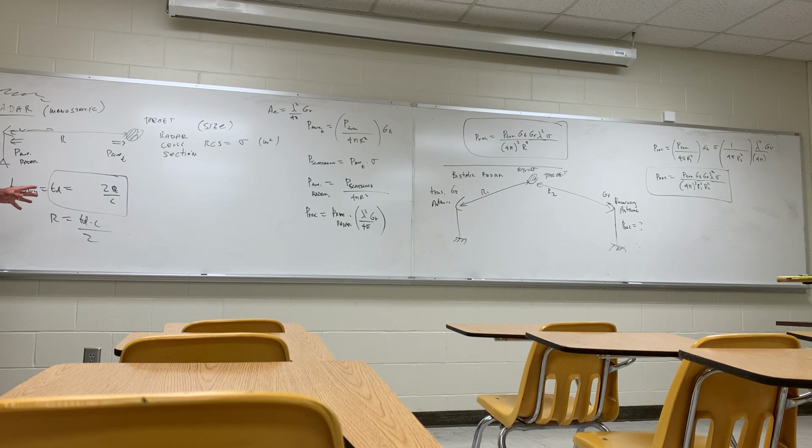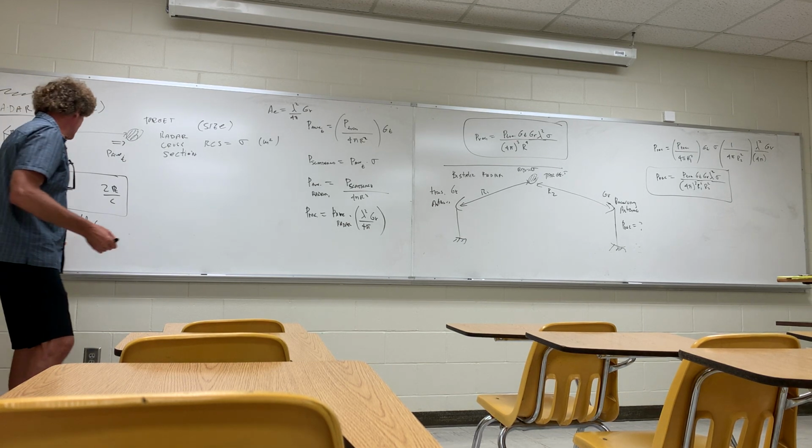It honestly is this simple. It gets much more complicated because what's actually sent isn't one pulse, it's a series of pulses, and they have a very unique temporal signature. So when you're getting echoes back, you use what's called a correlation function. In some cases, you can use convolution. And whenever you see the correlation function become a peak, you know that is the point that you can use as the time delay from when it actually occurs, and you know when you send the pulse. That's the way they do this. So that's what the range would be for this setup.